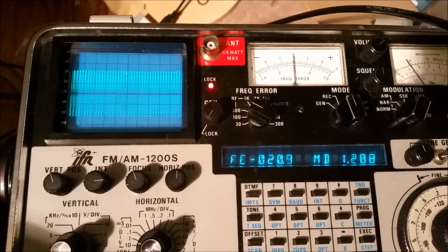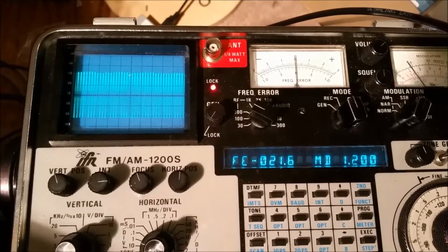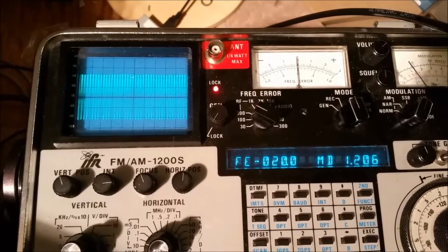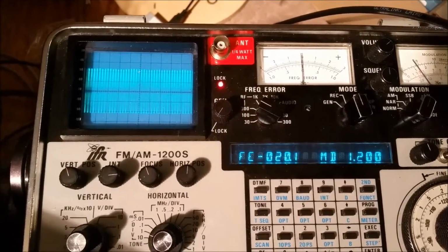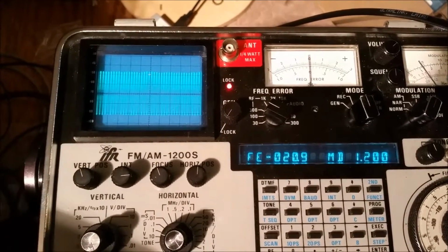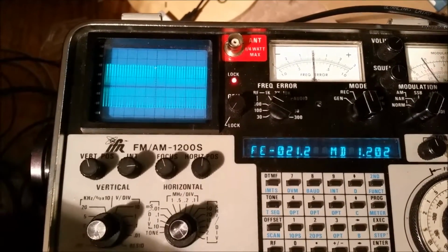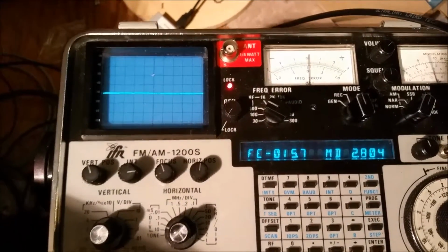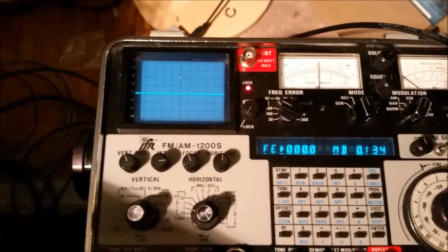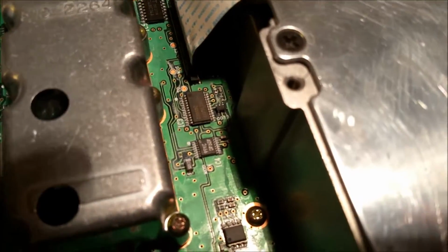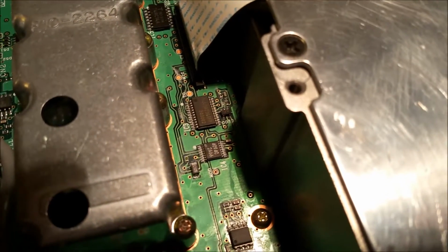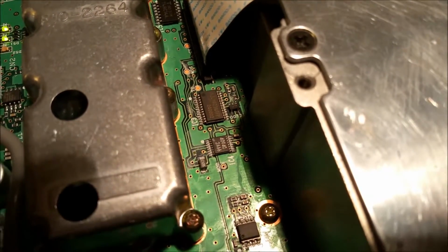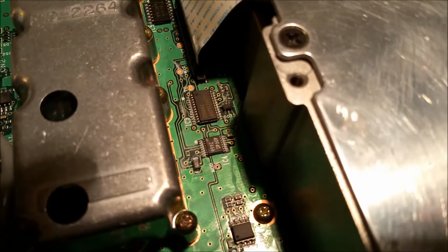Yep. Frequency falls off a little bit, but from about 400 hertz up to 4K, it's pretty flat. From the subaudible up to around 400 or 500 hertz, you actually get a little high frequency fall off. But there you go. That solves my problem. Essentially solves my problem. And it's an easy to get to point. You don't have to heavily modify the radio. I don't have to monkey around with all those op amps and circuits and stuff.